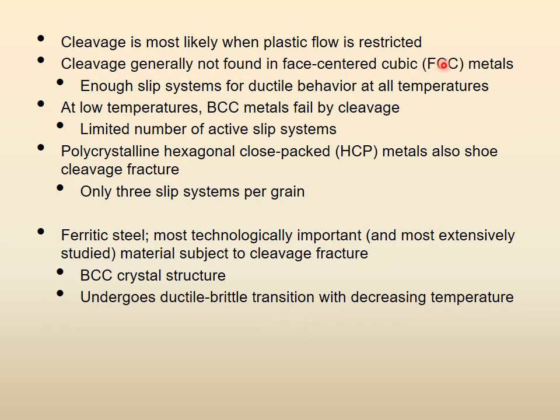We just told you that it is more preferable in BCC, and here we are again strengthening that it is not generally found in FCC metals. In FCC metals, there are enough slip systems for ductile behavior at all temperatures, at room temperature or higher temperatures. So mostly FCC metals will not break in a cleavage pattern.